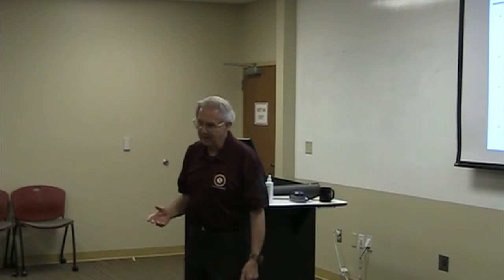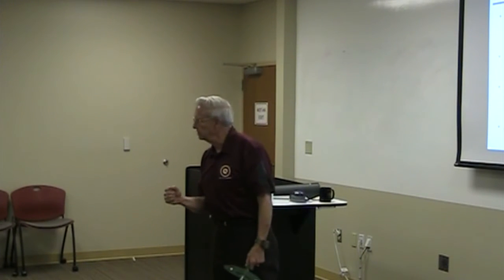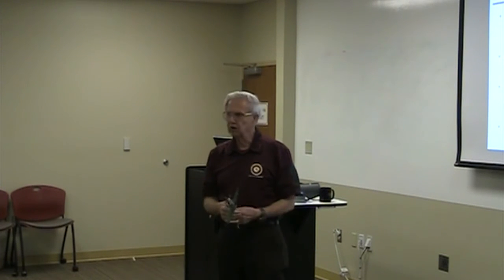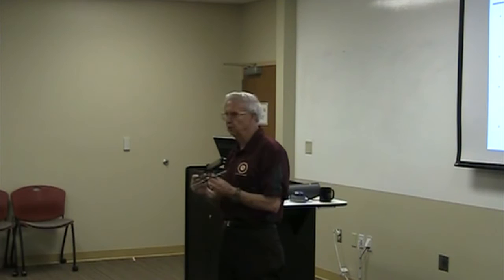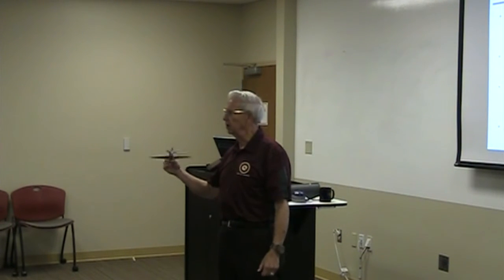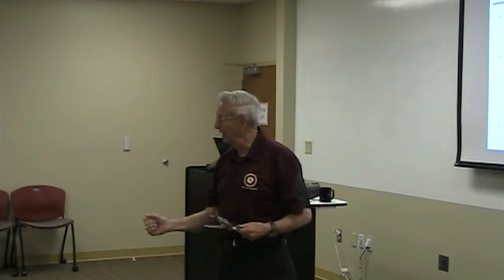But the other thing about the old T-33 was that the hydraulics in the ailerons gave the stick a deadband. You could always tell a new student on his first flight in the T-33 because he went out waggling his wings at everybody due to that deadband.